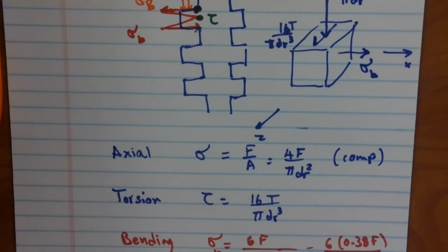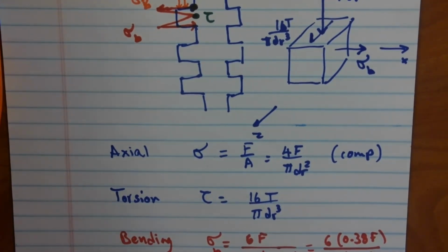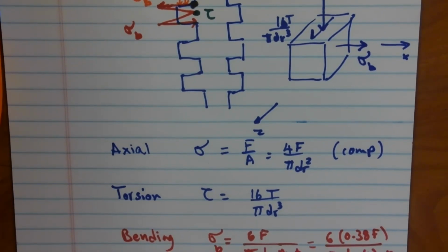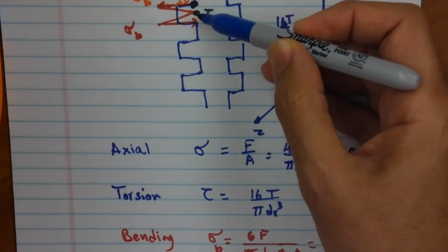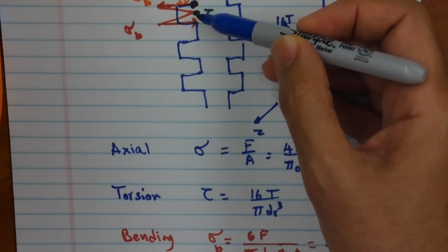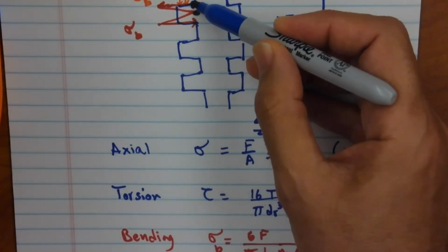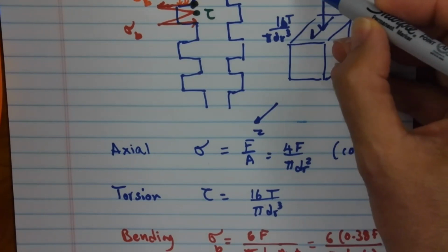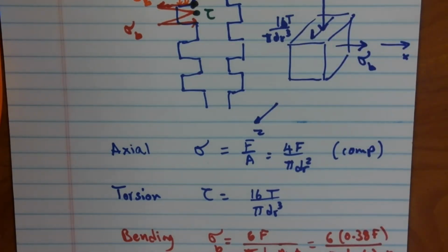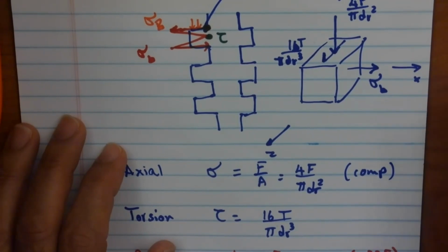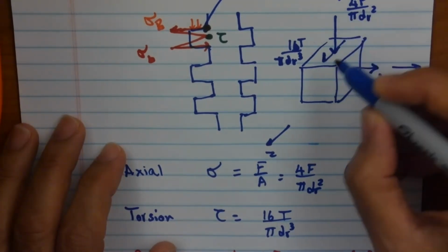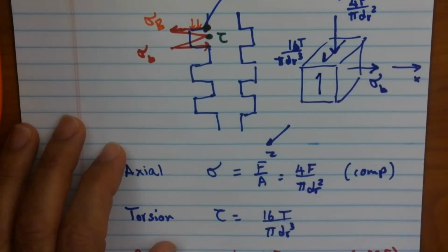How about the transverse shear? Should that be there? Where is the transverse shear stress acting? It's acting right here, right? It's in the Y direction on the X plane, correct? But it's right at the center of the thread, not at the root. And what I'm looking at here is this point. So this is the point that I'm drawing a stress element for. So this is why we ended up looking at these three stresses. And again, if I'm looking at this sigma YZ, I should also see a sigma ZY.